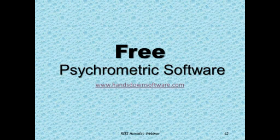I think I need to spin the sling for 2 full minutes before reading the DBT and the WBT. Is that correct? Well, in class just about a week ago, I showed the students how to use a sling psychrometer to deal with complaints on mold in a building, because that's what our unit was talking about. And in the classroom, it took me less than a minute to get 3 readings from my sling psychrometer, and the last 2 were the same.